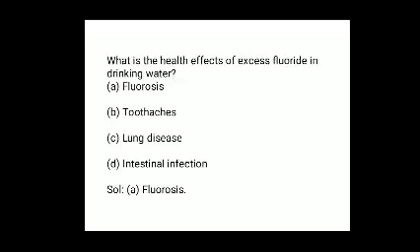What is the health effect of excess fluoride in drinking water? If the fluoride content is less than 3 ppm, it does not cause any harm to the body. In case it is more than 3 ppm, the water is fluoride contaminated. 3 parts per million.